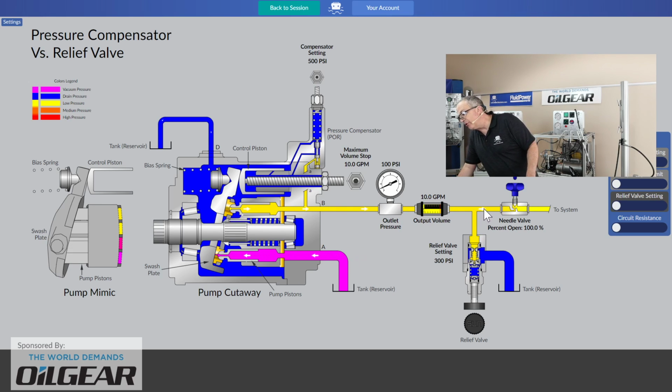Okay, the odd hydraulic system that we encounter does not have the relief valve teed in to the pump's outlet line right near the pump's outlet port, but the vast majority of them do. And in many a case, that relief valve is there in case of a system pressure spike coming back against the pump. The relief valve is typically the faster acting device.